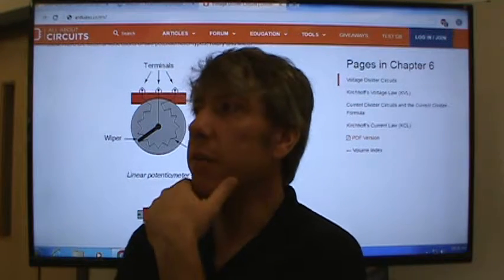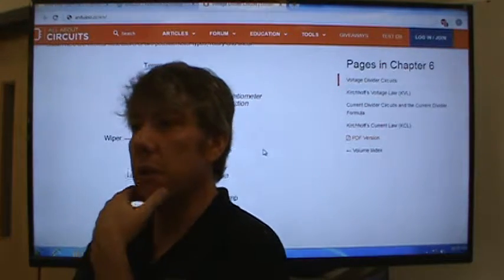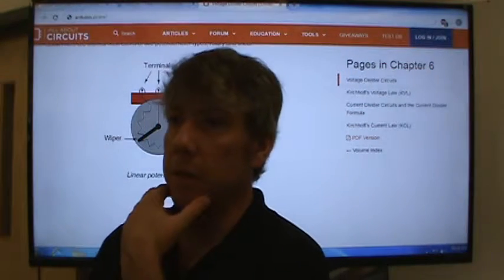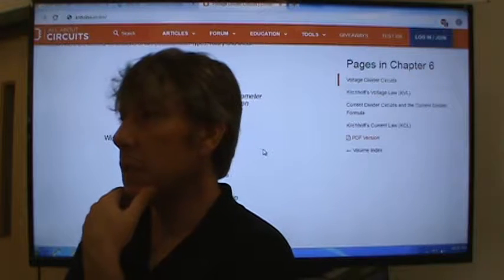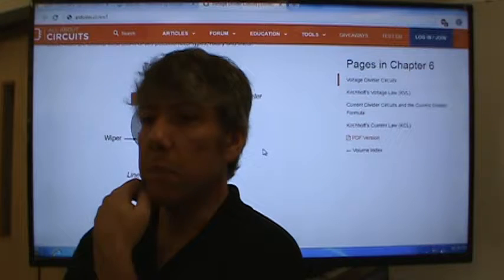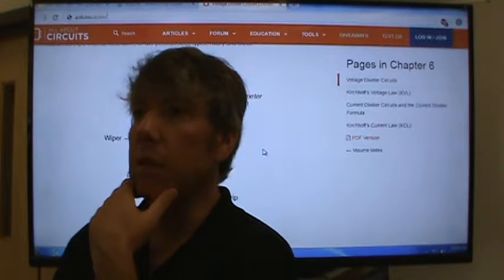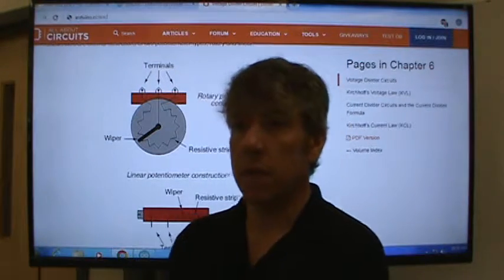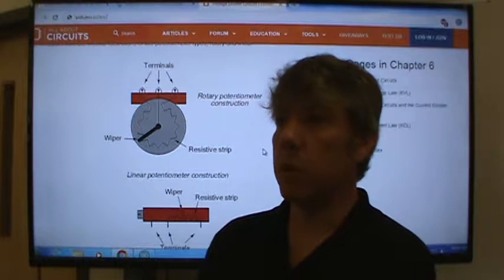Why bother? What about if it was 256? So 8-bit. What if they said, well, we don't want to waste 10 whole bits, let's use 256 instead. So let's take 5 volts and divide it by 256, which would be 8-bit resolution. So basically 0.02 volts. And they probably thought, well, that's probably not good enough resolution for some applications, so let's make it 10-bit resolution, which is very common. A lot of sensors, a lot of things are 10-bit resolution because that seems to be a good resolution.